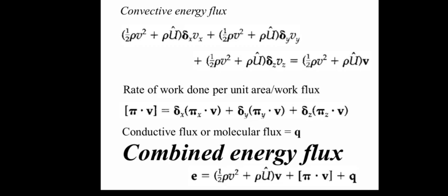Therefore, the combined energy flux vector provides a comprehensive picture of how energy is being transported in a fluid, taking into account both bulk motion and the molecular level interactions. The concept of energy flux is fundamental where we perform an energy balance on a control volume or a shell within a flowing fluid. The shell energy balance equation states that the rate of combined energy flux in minus the rate of combined energy flux out plus the rate of work done on the system by external forces plus the rate of energy production equals 0.